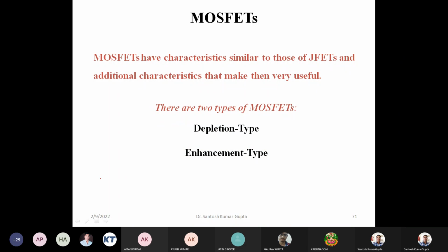When there was no reverse biasing applied at the gate in the form of VGS, we had the largest current, whereas when we applied a gate potential so that the PN junction at the gate is reverse biased, the current decreases.